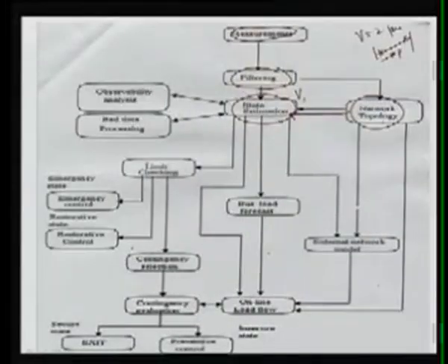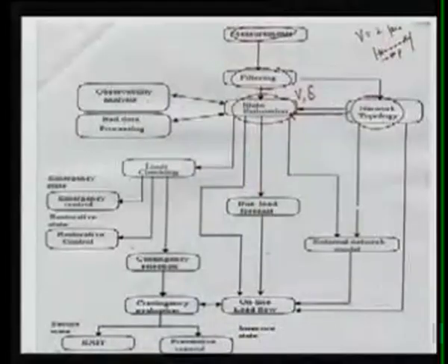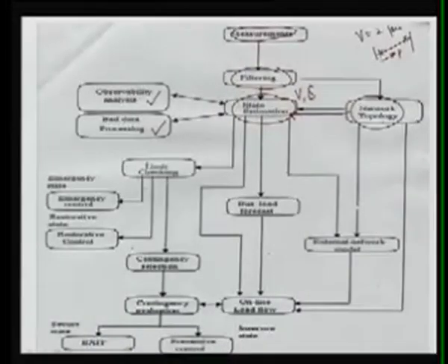Again, as I explained, state estimation is nothing but determining the voltage estimate as well as the voltage angle estimate. Now, state estimation is a broad process. Here we do two sorts of analysis. The first one is called observability analysis and another is bad data processing. In state estimation, bad data processing means we try to eliminate the bad data. There are many ways, with mathematics behind that, and we also perform observability analysis, by which we can say whether we can estimate our states accurately or not.